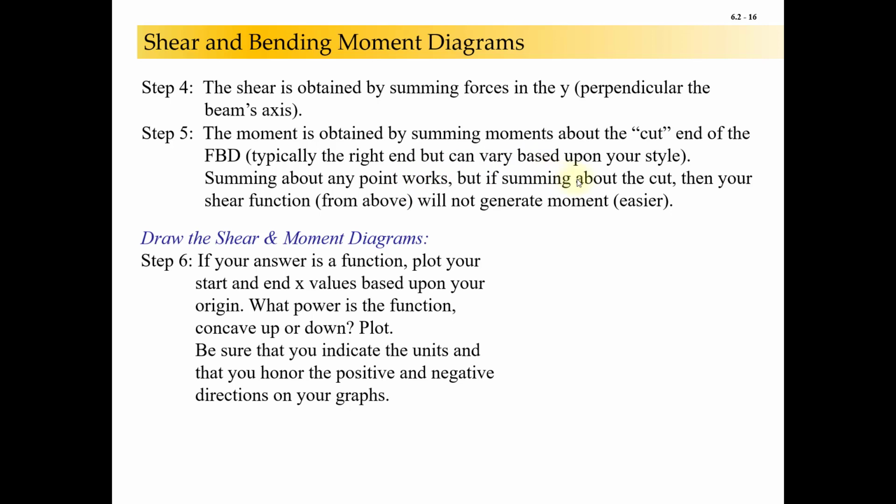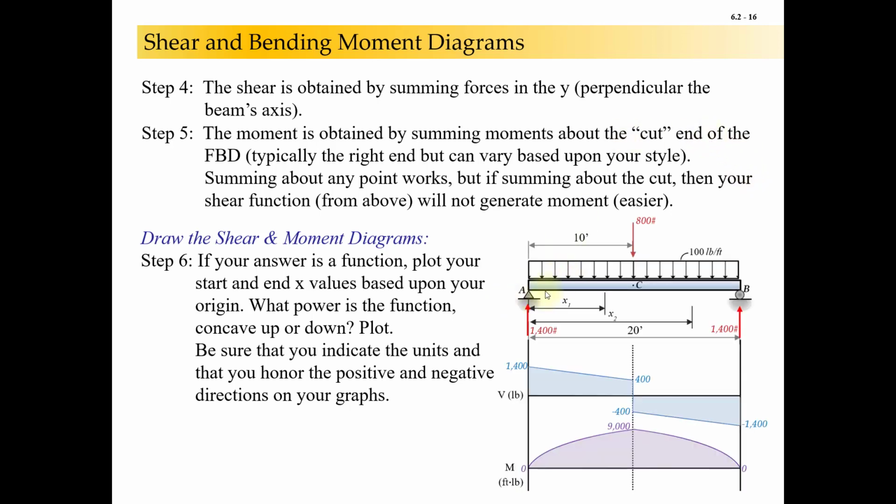And then we'll draw our shear and moment diagrams. If your answer is a function, then you plot your start and end values. You plug your start and end x values into your function and find the start and end values of your shear. Look at your function. Is it a line? Is it positively sloped? Is it a quadratic? Is it concave up or concave down? You can look at the math like you've been learning since high school and recognize how to draw these functions. So for instance, this beam right here would end up having a shear function that looks like that and a moment function that looks like that.